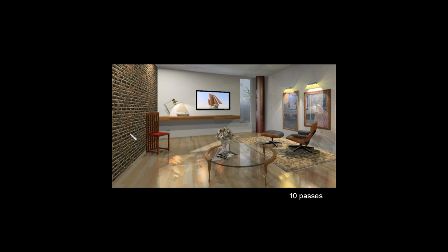So here's the same model after 10 passes. Now, the reflections are still kind of mirror-like, but you can see they are getting fuzzier. Here's the same after 20. Everything improving quite a lot at 20 passes. Here's 50 passes. Look at the floor. The reflections are getting fuzzier still. I'm getting more and more of that satin finish that I'm after. The lighting on the ceiling is much more refined. And now, at this angle, notice how textured, by just using auto bump, my brick wall looks.